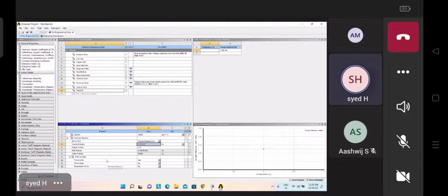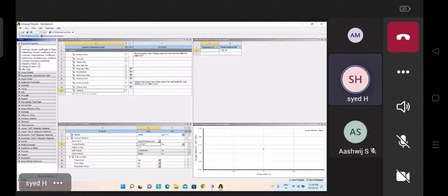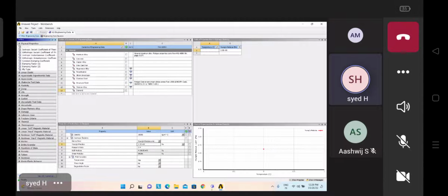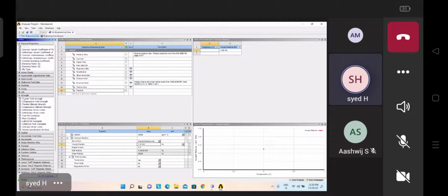See here, these are the important things we have to specify. Then the most important thing we have to place here is ultimate strength, ultimate tensile stress. Those things also are required here. So whatever properties you want, you can take here. You can place all the properties there. And plasticity, I don't want anything in plasticity. Strength, yeah, in strength you can find tensile yield strength.